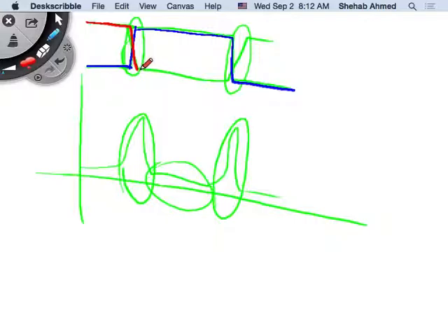Ideal switch doesn't, but a real switch does, because there's an RDS on for the MOSFET, right? So I squared times R is a voltage across the MOSFET, or there's a VCE across a BJT device, right? So there's a small value of voltage, and the current is flowing through the switch because the switch is on in this case. And then you turn the switch off, it blocks positive voltage, and current goes down to 0.